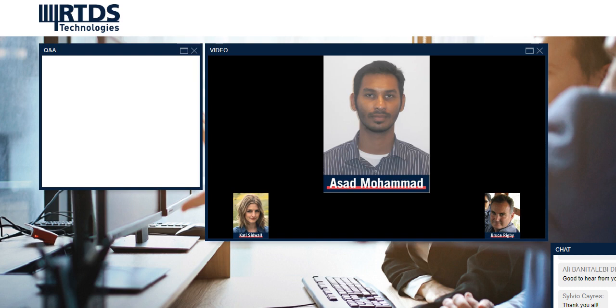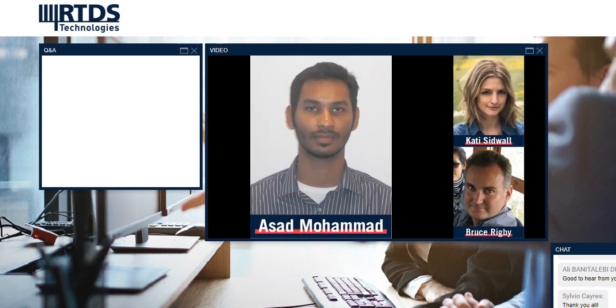So our tests were limited to knowing exactly what the algorithm could do and just trying to find errors in our own control system. But we would never try to understand how it's affecting the power system in general. If an event happens, we're not sure if it's affecting the stability of the system or not. So HIL, having a model of the power system we're testing, really enhances our performance in finding errors in our own control algorithms, or finding better solutions to validate.